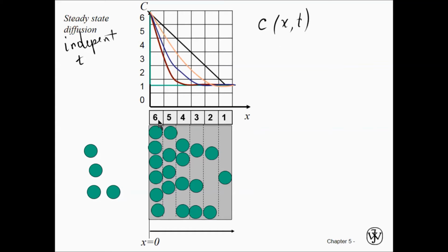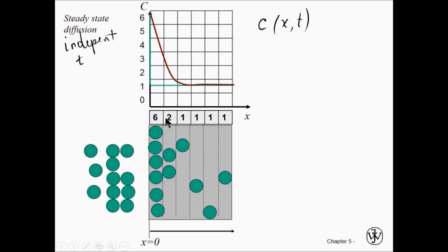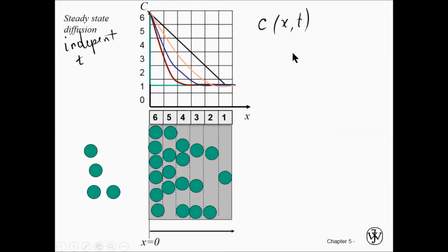If you see, when I move in position to the right, you see how concentration changes. So concentration is a function of position, and plus, so far you see that when time goes, you see changing concentrations over here. This concentration is a function of time also, until some time. Now if you see this straight line over here, when you have steady state diffusion, what we do is we create equal pressure at both sides of this aluminum bar, let's say.